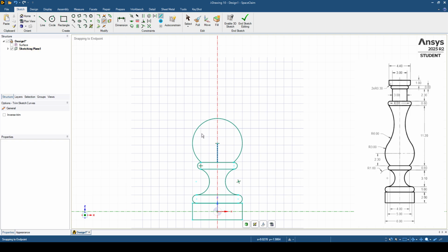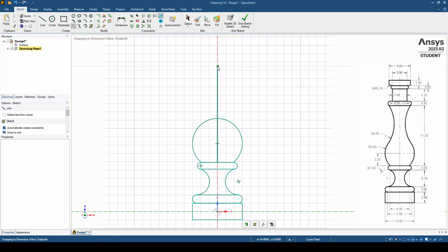As we did before, in order to draw this arc, I'm going to draw first the upper rectangular form, then we can draw the arc. So choose construction line again. From this line to above, it's actually 11.2, and to the middle we have to add 0.4, so we are 11.6 millimeter away.